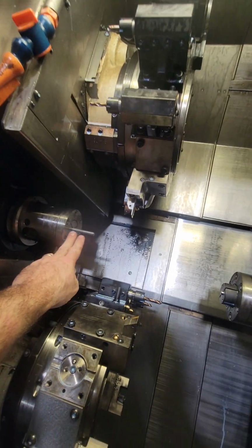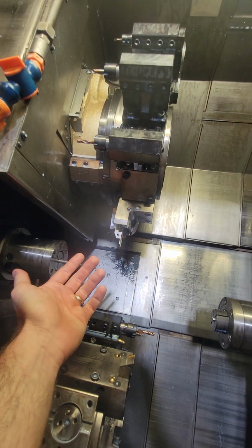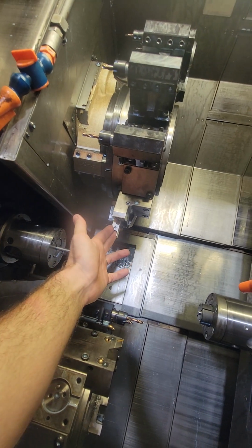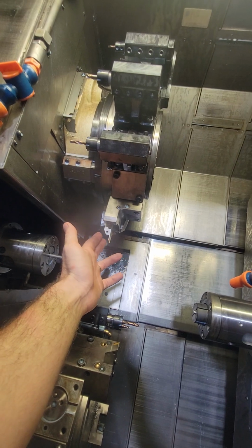So basically the way this works is that, through the parameters, you can set up a call, and it'll be an M code. I'm using M700 for a cutoff call. I have a bunch of macros that I'm reading through the program and setting, and anytime I do an M700, it'll call the cutoff tool up. I always use tool 12, so that never changes.